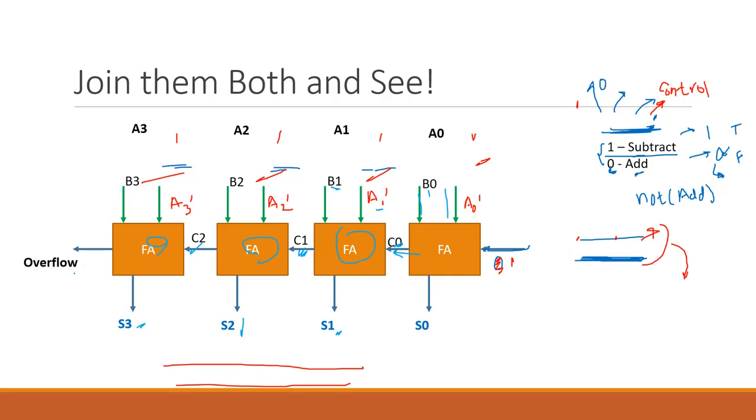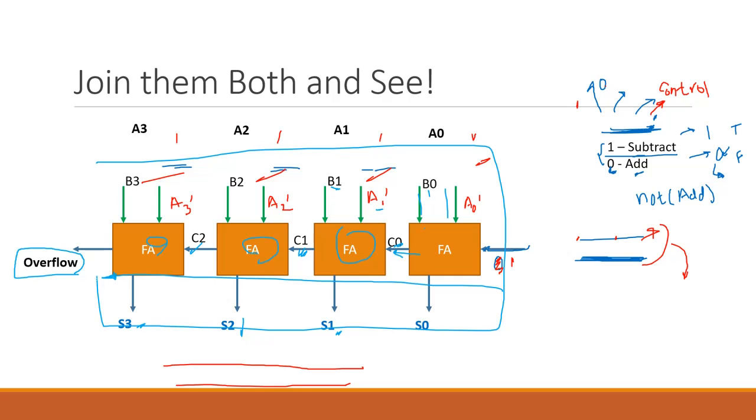So that means this last overflow bit will take the maximum amount of time to get generated. That is the worst case path in this circuit. This path. This is the worst case path. So imagine if this entire thing is encapsulated into one big block and you are using multiple of these blocks over here.